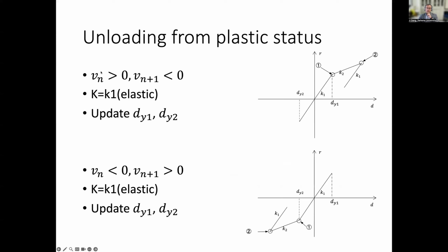But once the velocity changes from positive to negative, or from negative to positive, like originally you are going in the positive direction but suddenly you change to this direction, then we know that you are unloading. The stiffness will change back to the elastic stiffness.